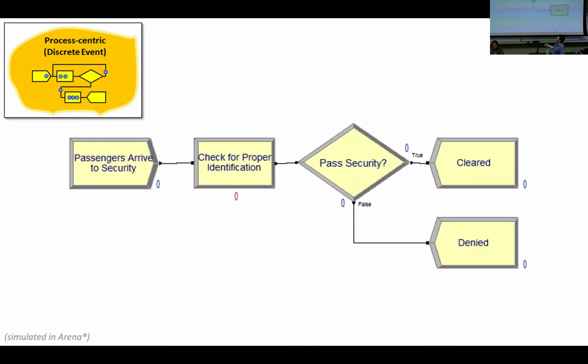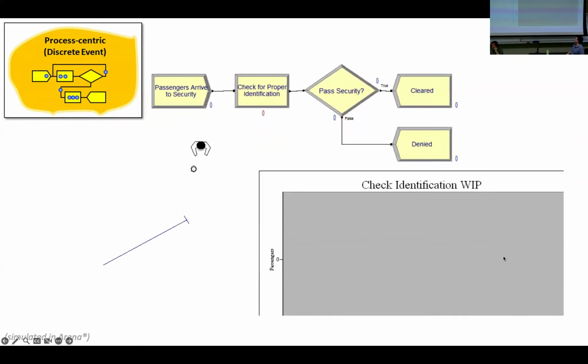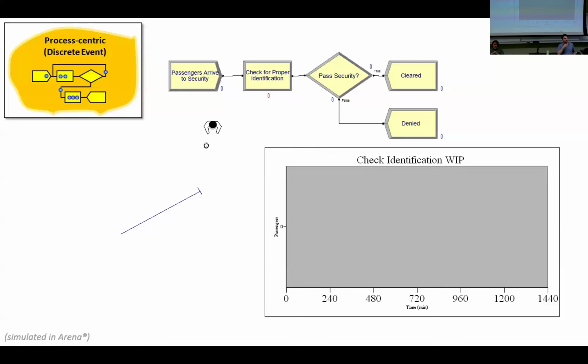It's a very simple model where we're going to have a number of entities in every box. You're going to say how many people are arriving right now, how many people are in line waiting to get checked, how many people passed, and how many people were rejected. With a simple model like that, we can add more interesting visualizations. So as this same model runs, we can put a little line up here where we've got a document checker that's always there. We're going to learn that we call that a resource. The things that are always there, the things you have to wait on, those are resources. And then the entities line up here at the end of this line waiting to get access to that resource.